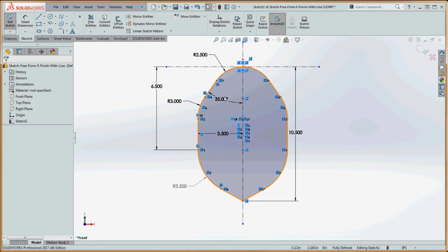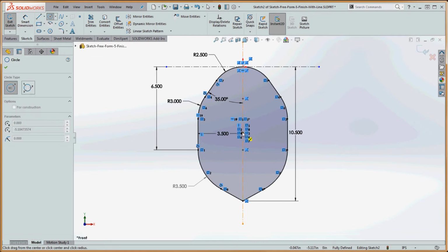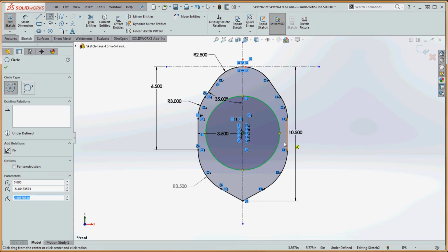So you'll notice up here that we do have kind of a gray shadow background in here. SolidWorks puts that there to let us know that we have enclosed geometry. We don't have any gaps in our model. If we had a gap in the model, it wouldn't be gray. And one interesting thing about this is, as a real quick aside, if we continue to add enclosed geometry in here, maybe we put some additional circles in here, the additional geometry gets darker and darker.